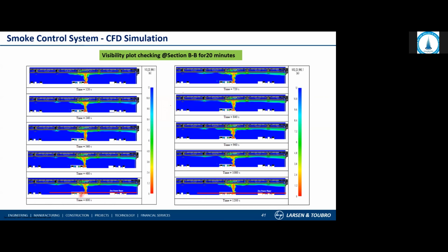So here, if you see, the fire source is here, and smoke is generated. Once this is there, through the fire alarm, the fan will be actuated and directed so that the smoke can evacuate. Smoke always travels vertically, touches the ceiling first, then spreads horizontally, and slowly gets down. The moment fire alarm actuation happens, the smoke exhaust starts immediately, and we get visibility, and people can evacuate from the building.